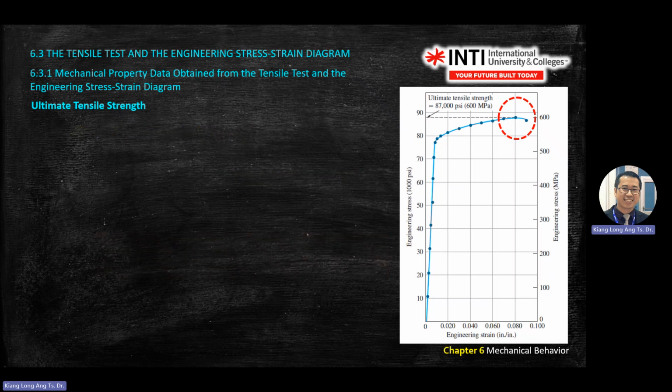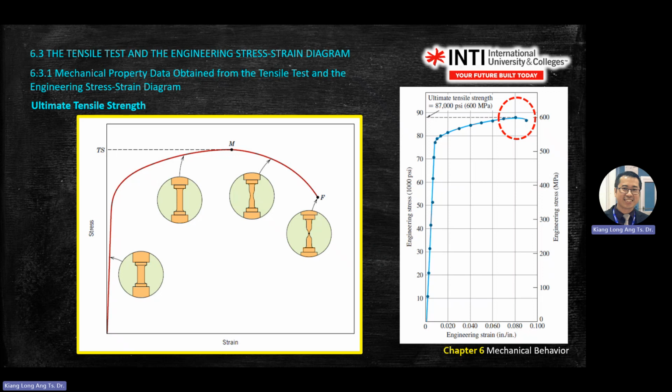Okay, the rest you read. So this is the illustration of the point on the line. Sometimes the question will give you 3 marks, asking you to draw what happened to the tensile sample. Just 3 marks. This one only happens in test, it won't happen in final. This one will just return to original shape. This one starts to become thinner. And after the end point, the maximum tensile strength, it will show necking. This one is a failure already, it starts to break.